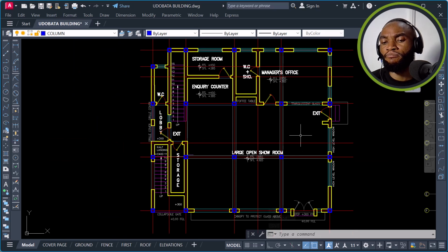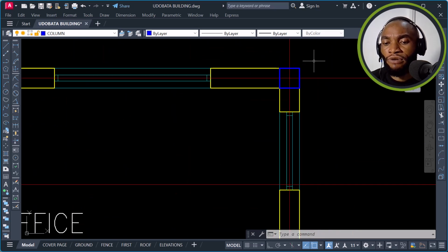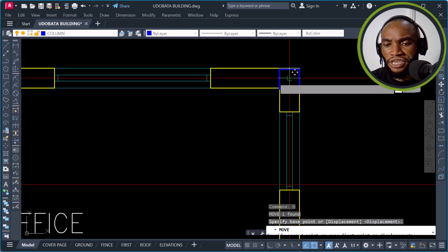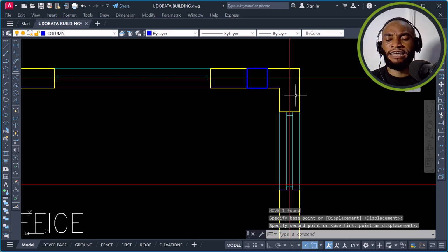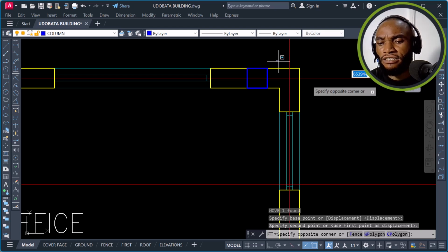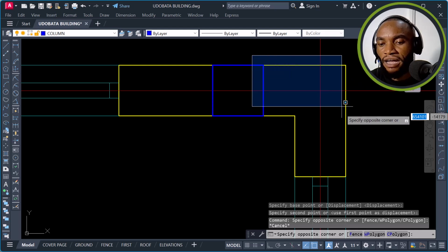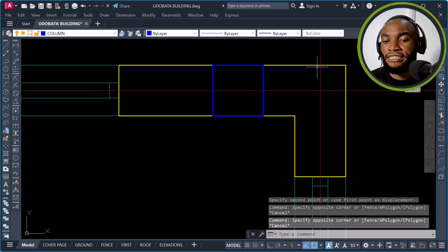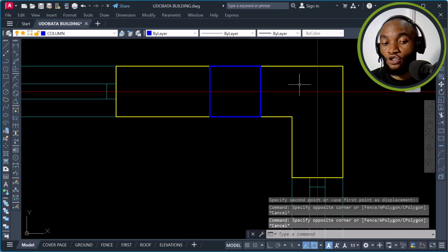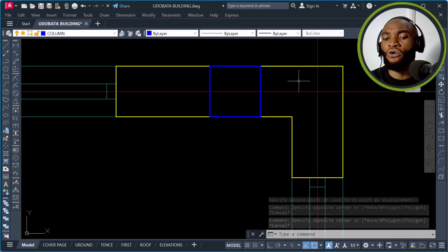Now, once you've picked a point, now that this is an edge, we cannot just come and put our column, let me say, here. It doesn't really make sense to be here, all right? Why not push to an edge? This is the point where they will meet. Why have a small cantilever beam here? No. Instead, as long as this point will not disturb the appearance of the structure, push it there, okay?